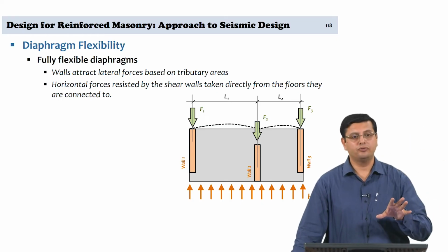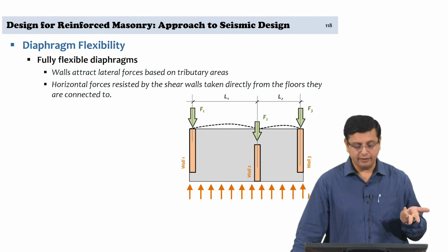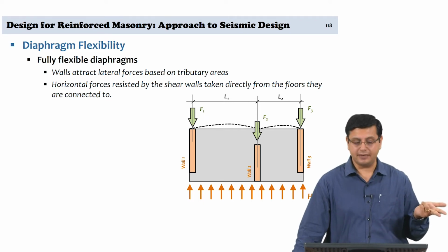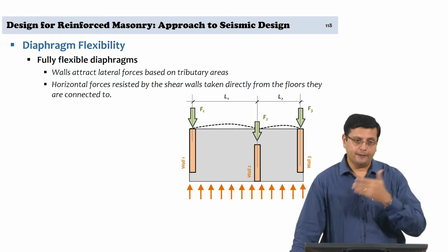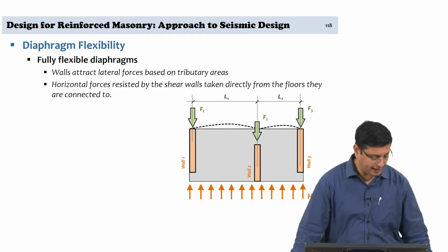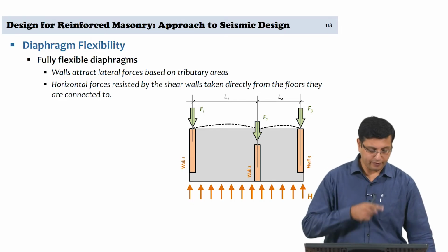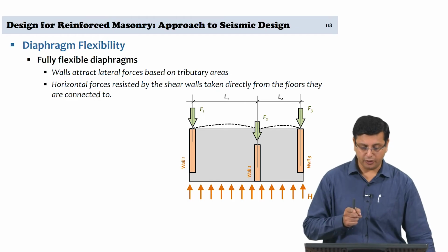We have those forces, we can do in-plane flexural wall design, out-of-plane flexural wall design, where we use PM interaction diagrams, and design for shear and design for axial force. So, that closes the loop as far as the design from component level to system level is concerned. We have come back to the component level. To conclude, I am actually going back to where we started from, which is something that we have talked about, but not looked at specific details.